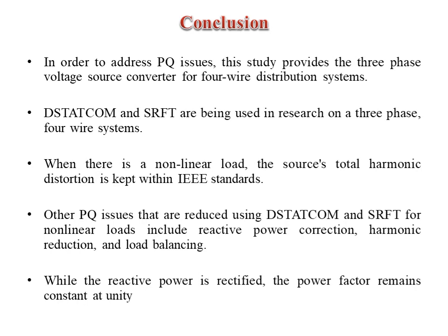While the reactive power is rectified, the power factor remains constant at unity, which is shown in the waveforms of voltage and current at the point of common coupling. Thus, with the help of this Dstatcom, we can reduce the power quality issues present in the three-phase four-wire distribution system caused due to the connection of non-linear loads.